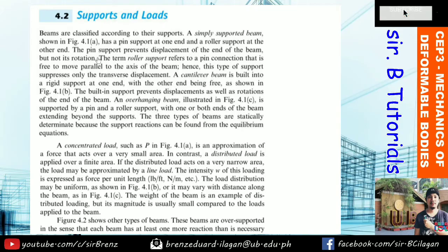So meaning yung pin mo, ang sinusuportahan niya lang is yung displacement niya. Kaya dalawa yung reaction natin: we have vertical and horizontal. Pero yung rotation niya or yung moment, wala siyang sinusuportahan doon. And then, the term roller support refers to a pin connection that is free to move parallel to the axis of the beam. Meaning, wala siyang horizontal reaction. So, vertical lang or perpendicular to the surface. Okay? Hence, this type of support suppresses only the transverse displacement.